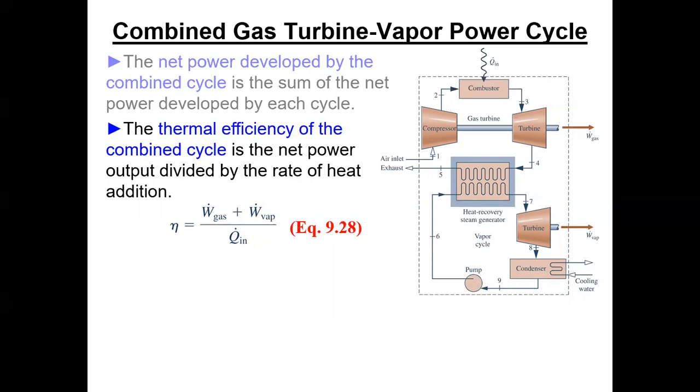Now, in reality, these heat recovery steam generators usually have what they call duct burners, and they can inject additional heat. They can burn additional natural gas to heat up the turbine exit to a higher temperature before it goes into the steam generator. They'll run that duct burner during times when they need extra generation capacity. So you have some baseline generation without the duct burner, and then they'll probably get an extra 20 or 30% out of the unit if they fire the duct burner.